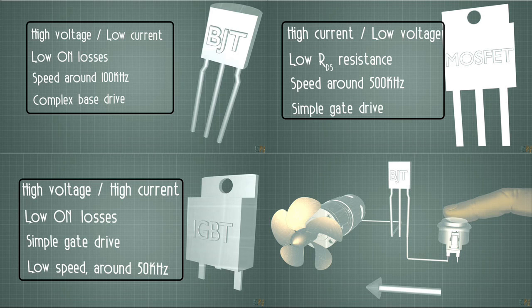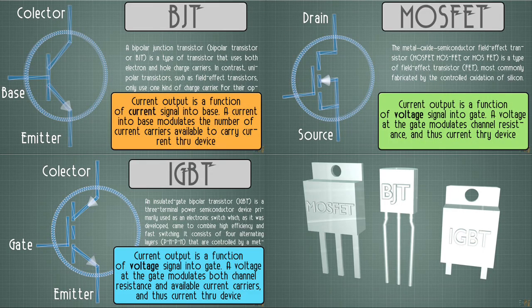Fourth is performance. Silicon BJTs have a higher current gain and better switching characteristics in most applications compared to germanium. Germanium BJTs, while historically significant, are now niche, used in some audio applications for their unique sound characteristics due to lower turn-on voltage, which is 0.3 volt versus 0.7 volt for silicon.